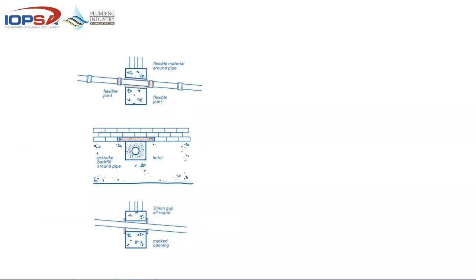Whenever there's a pipe either crossing or penetrating a structural element, or whether it's found to be under that structure, like in this case was penetration, or if it needs to be removable afterwards, then we still need to look at these three options from 10.400 Part P and 10.252 Part 2 drainage perspective.